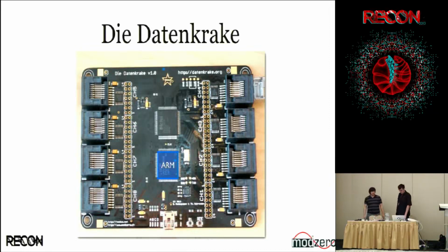So here we can see very quickly the ARM. Above it is the FPGA. So now we should see the USB, or no, one more. Is it USB? So here's the USB. You see the USB comes in through the bottom. We have a newer generation FTDI. It's an FT230X, which is basically, as far as I know, the 45 nanometer silicon that FTDI uses. So for you software guys, that means it's just newer and cheaper.